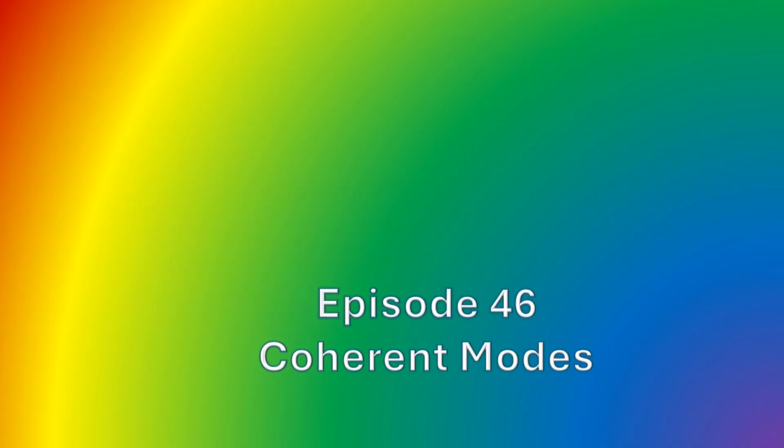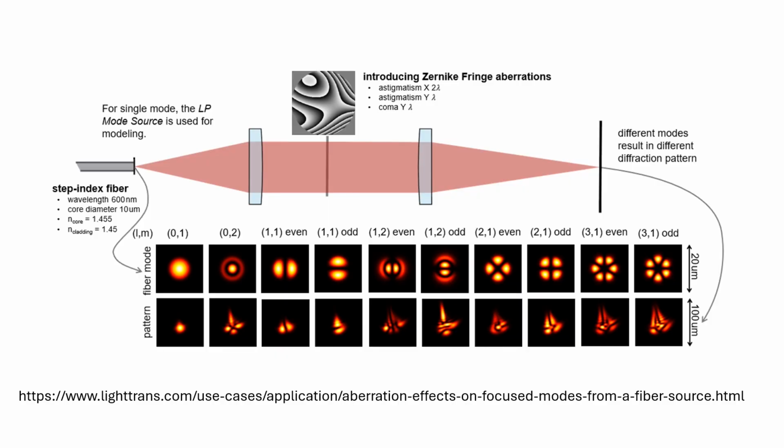Episode 46, Coherent Modes. Here again is this concept of a mode. So we have a fiber coming in. The fiber is a step-index fiber, so it has these different spatial distributions that satisfy the boundary conditions at the edge of the fiber and are propagating modes, and they create different spatial patterns. In this case, there's a modulator here in the middle that transforms those into different spatial patterns. But since this is a reversible system, these modes will remain orthogonal, and this comes from the lighttrans.com website.